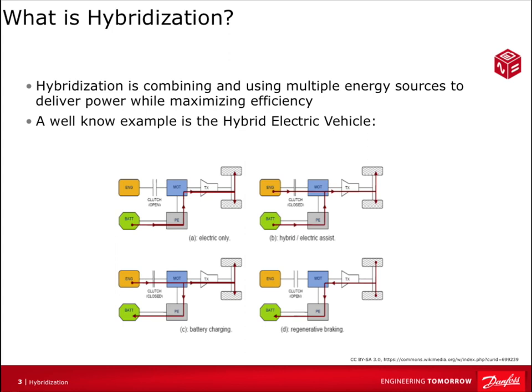And then finally, there's regenerative braking. In this situation, we convert the kinetic energy of the vehicle into electrical energy, and we charge up the battery while braking the vehicle to a stop. In particular, with a normal combustion engine vehicle, we would have had to dissipate that energy through mechanical brakes, which would have dissipated that energy into heat energy, which is considered to be a waste.